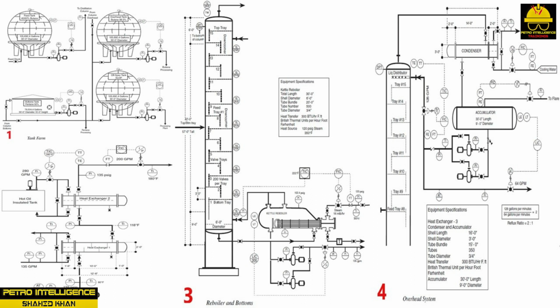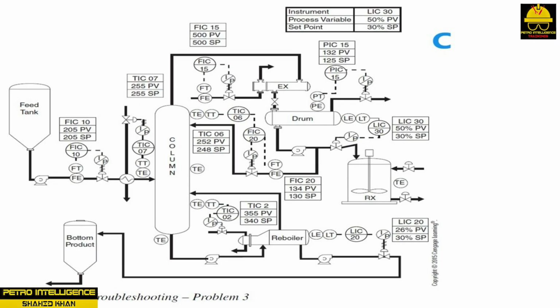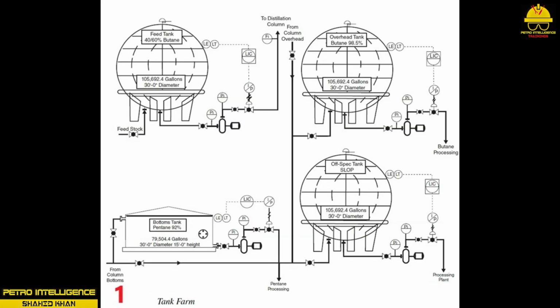Follow the following steps for the startup of the distillation unit. 1. Notify your supervisor and all concerned, i.e., engineering, maintenance, etc. 2. Ensure all safety hazards are secured. Trash, locks, old permits, etc. 3. Check equipment and instrumentation. Stroke control valves 0 to 100%, check lineups, etc. 4. Sample feedstock. 5. Line up feed tank to heat exchangers and column. Check each valve lineup.